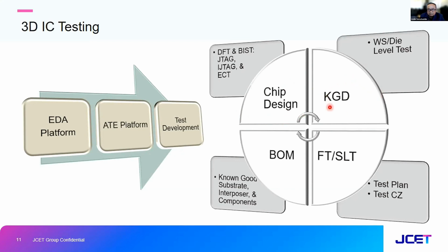And then you may also consider this known good die program in collaboration with the OSAT. It varies, because based on my experience dealing with this kind of strategy, the customer may need to include the KGD program even up to the wafer level tests in this case, or the RMA test on a prober, a film frame prober. That's a good example where the customer will use the RMA testing in order to make sure of the delivery of only good die or good units in this case.